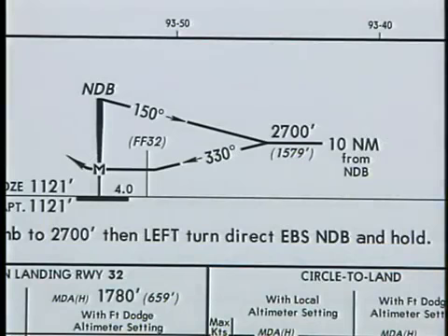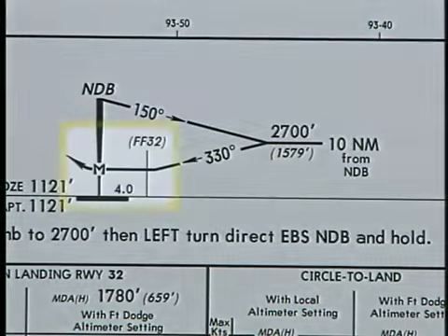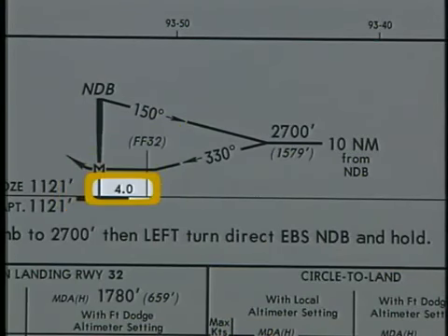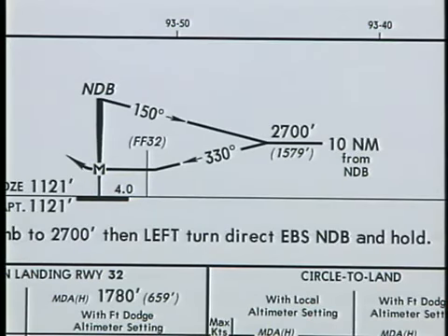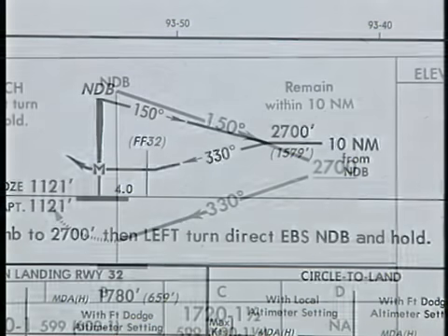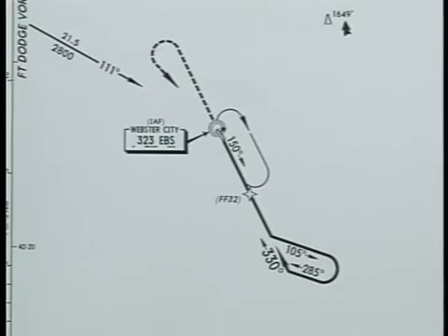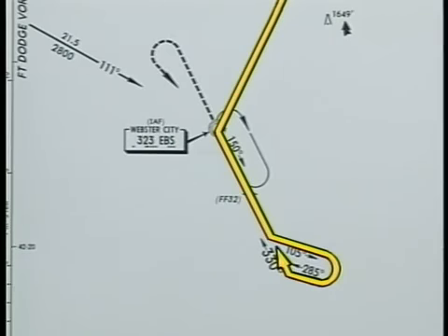If a final approach fix or step-down fix is not named in the approach procedure, a sensor final approach fix is established at least 4 nautical miles from the missed approach point. These sensor fixes are identified in the database and appear on Jeppesen charts, but do not appear on NOS approach charts. Flying a GPS procedure is identical to flying a traditional approach. The same approach track is flown and the same minimums apply.